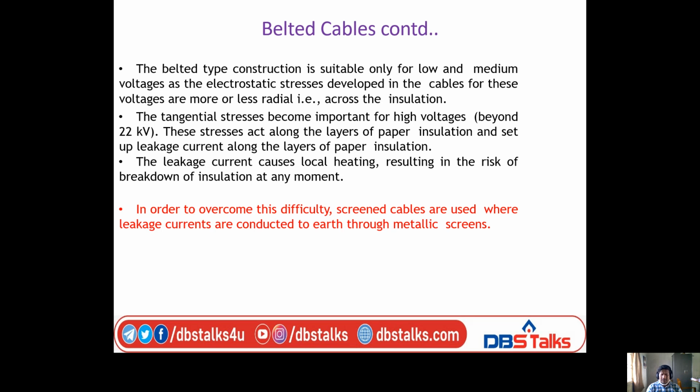Now coming to belted cables, these are suitable for low and medium voltages, such that the electrostatic stresses developed in the cables at these voltages are more or less radial, that is, across the insulation.